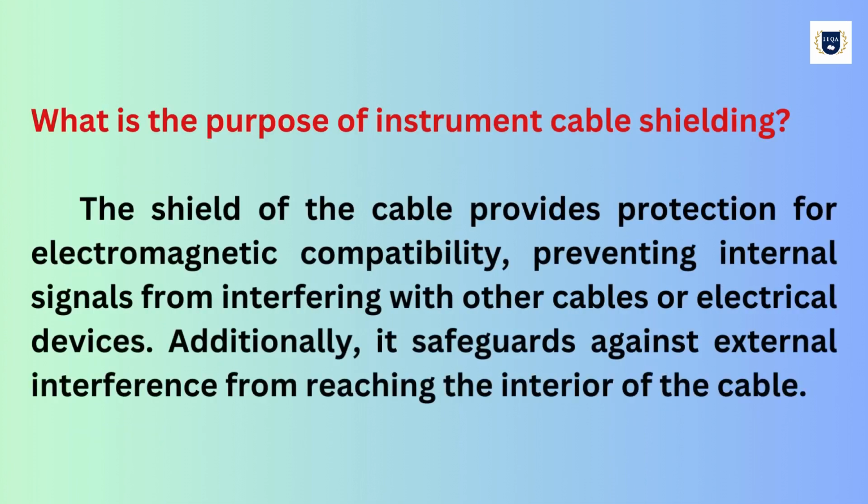What is the purpose of instrument cable shielding? The shield of the cable provides protection for electromagnetic compatibility, preventing internal signals from interfering with other cables or electrical devices. Additionally, it safeguards against external interference from reaching the interior of the cable.